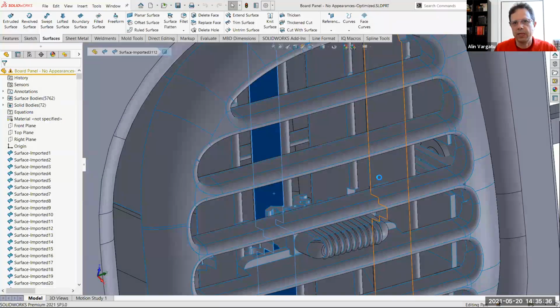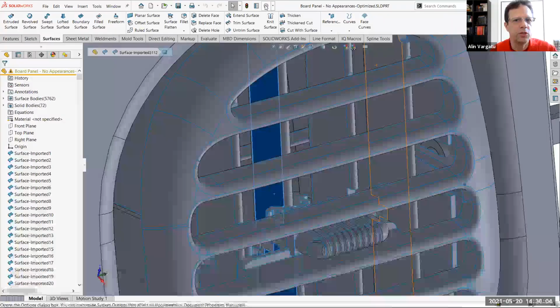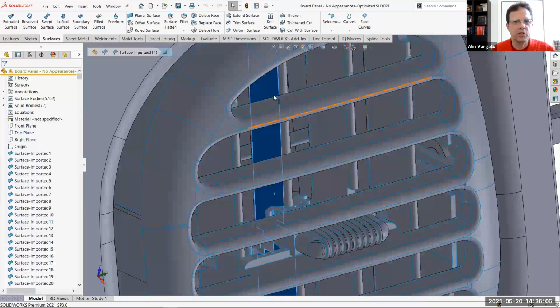So those of you who attended my other presentation, the one that I did with Artem Taturevich on API for large assemblies, you remember we have a little button that can turn on and off this functionality. And it's also much faster than doing this manually. You can see how this circle is spinning now, because when you change one setting in system options, guess what? SolidWorks rewrites all the settings, not just the one that you changed. So it's not very efficient, right?